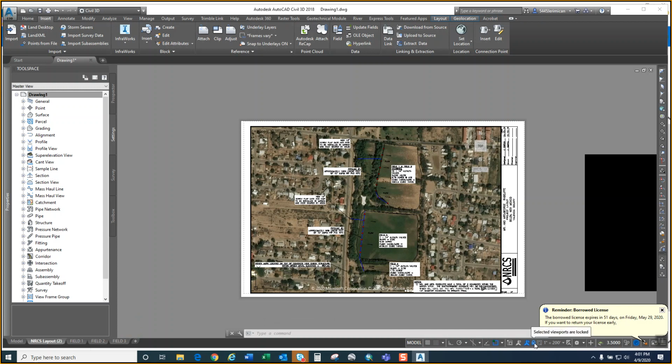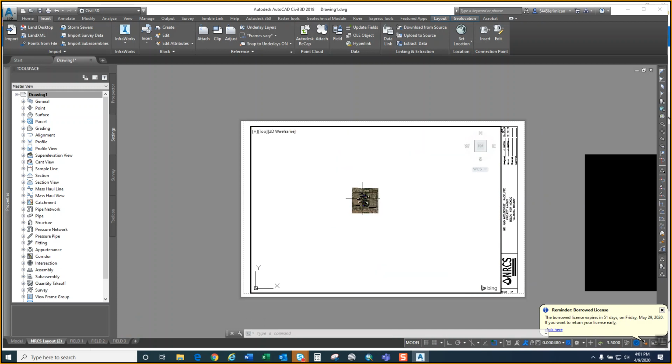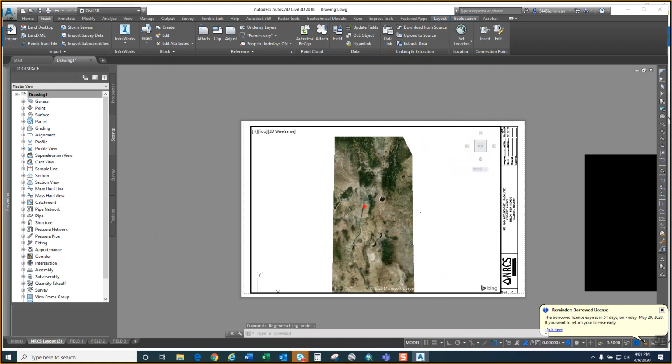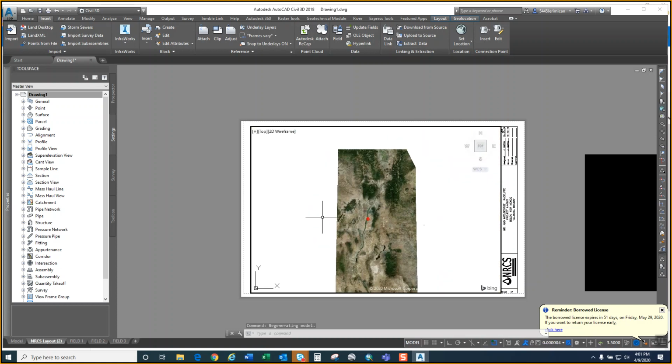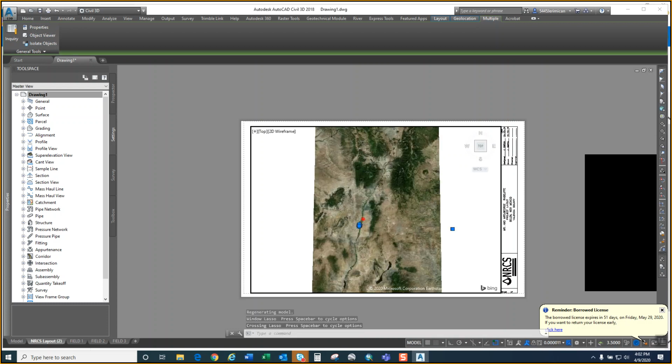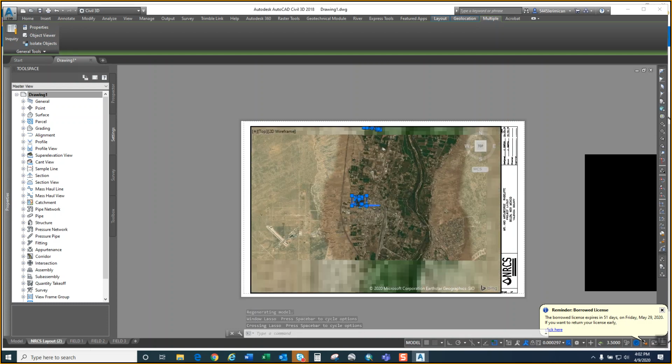I'm going to unlock my viewport so that I can zoom out, and zoom out even more. And then I'm going to just type the command, oh shoot, regen all. If you can't see all your points, then regen all. And I'm going to pan over all this, and my points should be in here somewhere. They should highlight. So let's see what we got.